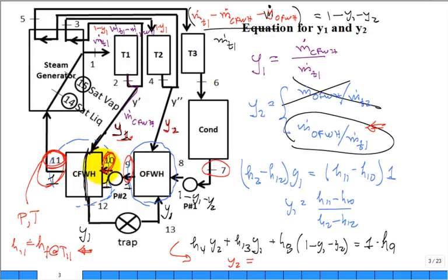How many people did the H of 10 because you knew the pressure and you knew the entropy, and then found the work of the pump that way? But you found that it's a lot different than using VDP. True? Did you try both ways? It's a lot different, because we're linearly interpolating, and if you're in no man's land in the table, far away from pressure and far away from temperature, your interpolation isn't that good.